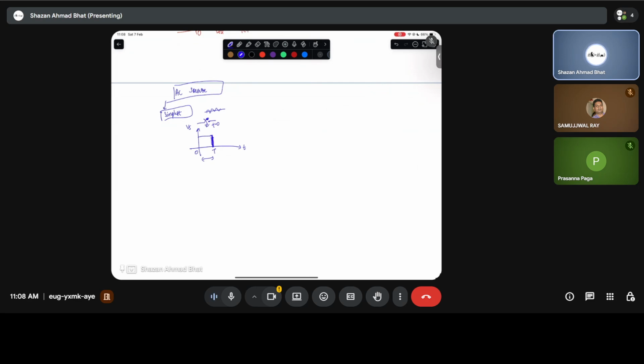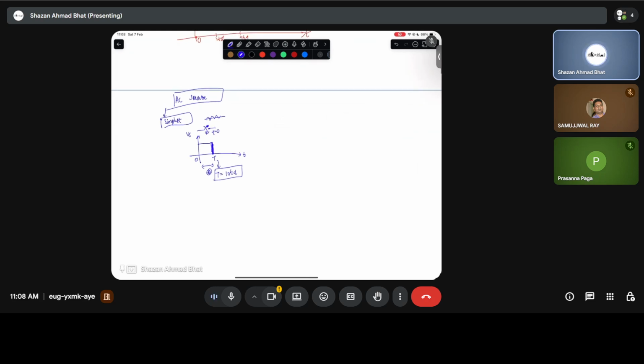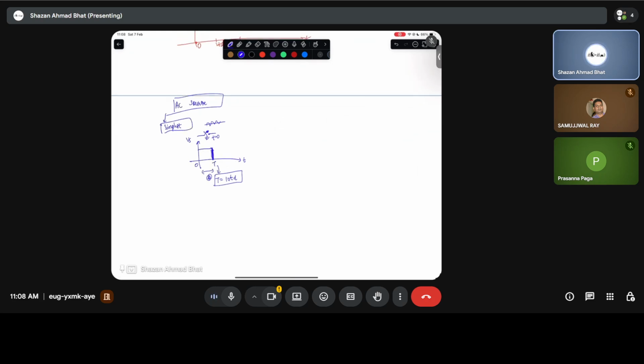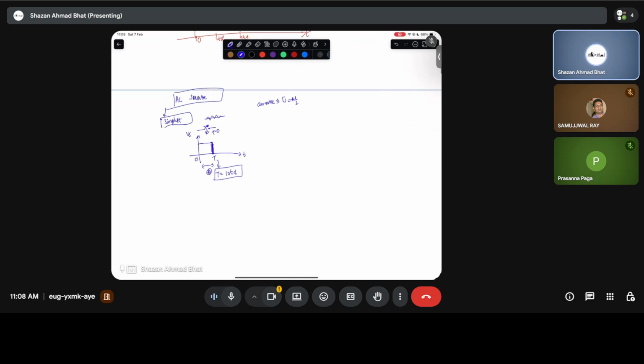And let's assume that this time period, which is time period t, is approximately 10 times td, which has been discussed in the notes. So that means it's 10 times the delay time in the transmission line. Okay, so now how will you draw the lattice diagram for it? Also assume that the reflection coefficient from the source end is plus 1 by 2, and the reflection coefficient from the load end is also 1 by 2.